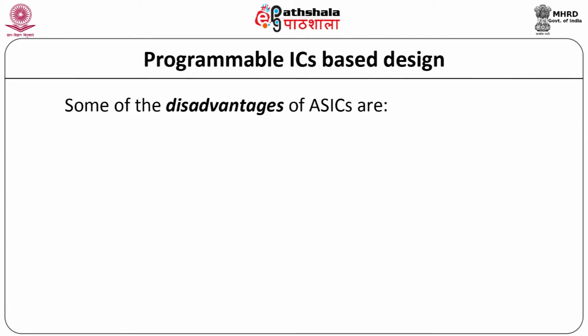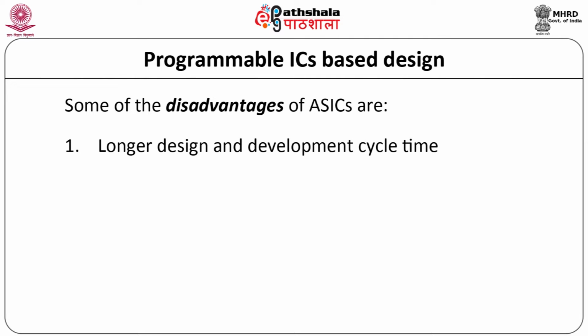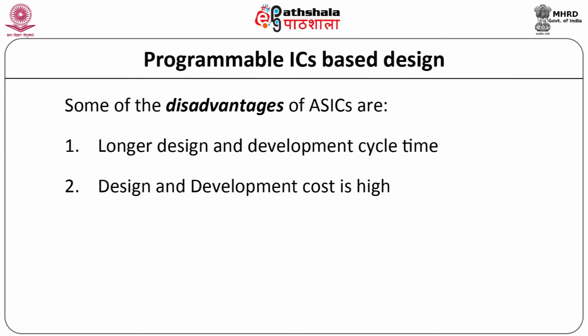Let us now discuss some of the disadvantages of application specific ICs. The first disadvantage is longer design and development cycle time. Usually ASICs are mask programmable, hence the design and development cycle is longer and takes more time. The second disadvantage is that design and development cost is high.